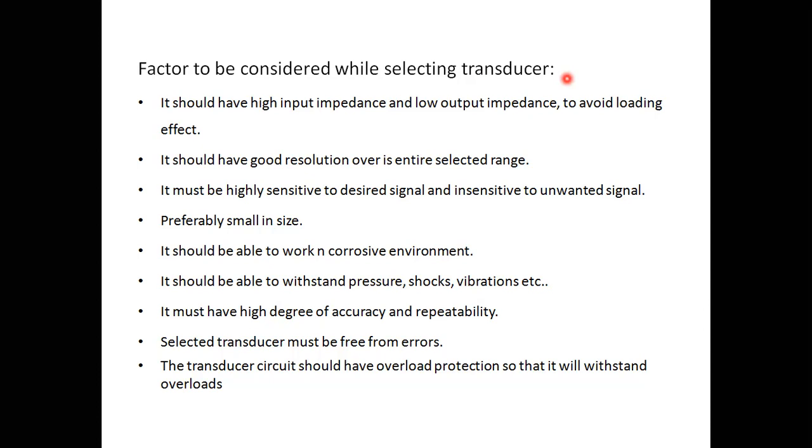The instrument must be highly rugged, meaning it should be able to withstand loads, and it should have high input impedance and low output impedance to avoid the loading effect. The instrument must be very small in size, and it must be optimally sensitive. Why?